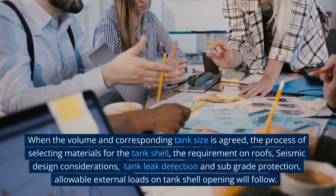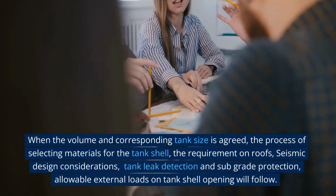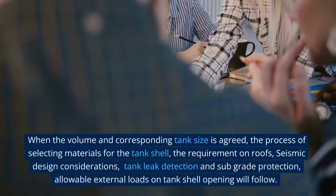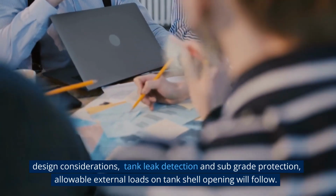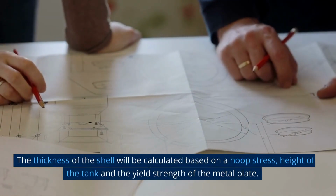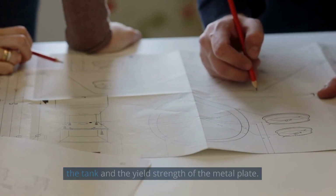When the volume and corresponding tank size are agreed, the process of selecting materials for the tank shell, the requirements on roofs, seismic design considerations, tank leak detection and subgrade protection, and allowable external loads on tank shell openings will follow. The thickness of the shell will be calculated based on hoop stress, height of the tank and the yield strength of the metal plate.